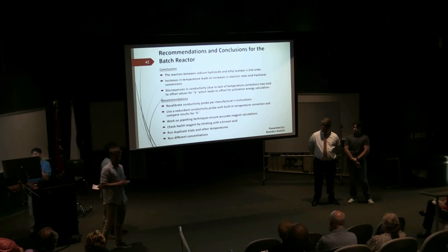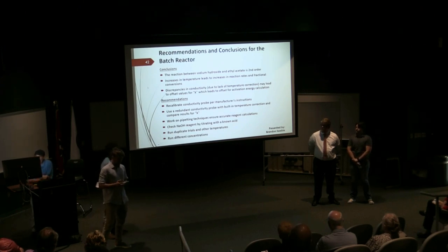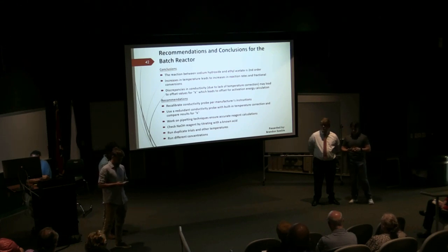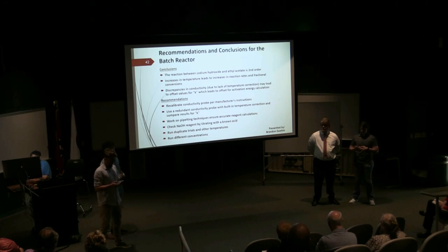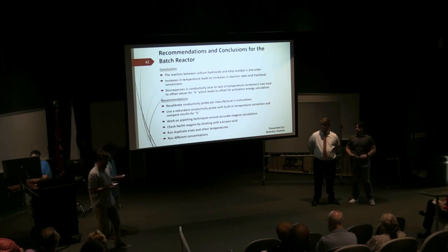Here are conclusions and recommendations from our batch reactor. Some conclusions: we confirmed that we have a second order reaction. Conductivity issues could impact K values and activation energy. Some recommendations: use a temperature corrected conductivity probe, improve pipetting accuracy, and run duplicate trials with varying temperatures and concentrations.